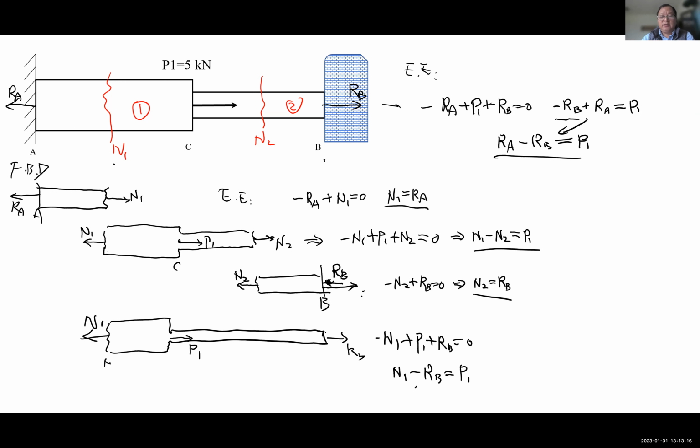All right. So we basically have one fundamental equation. That's sigma Fx equals 0, right? If you look at this here. So fundamentally we have one equation there, and we have two unknowns. So we cannot determine. Based on the equation, you cannot find N1, N2, because there are two unknowns and you only have one equation. That's it. The key equation is just one.